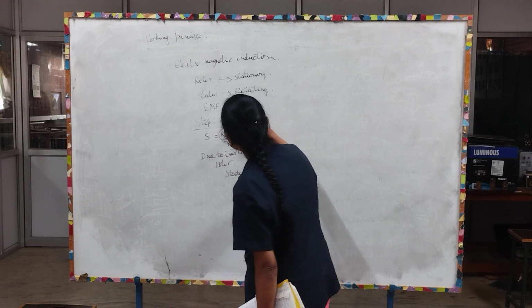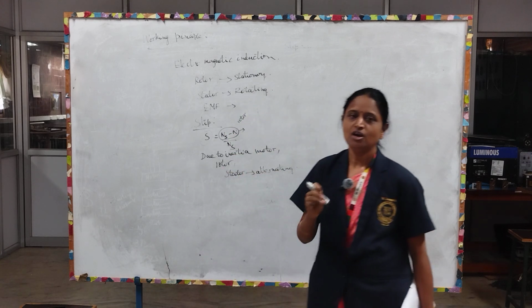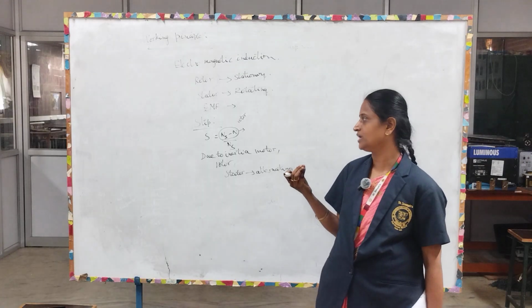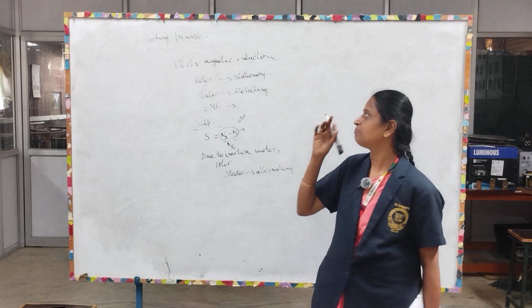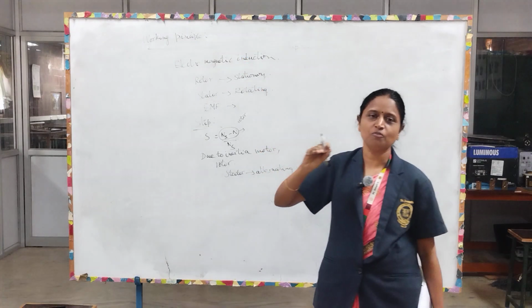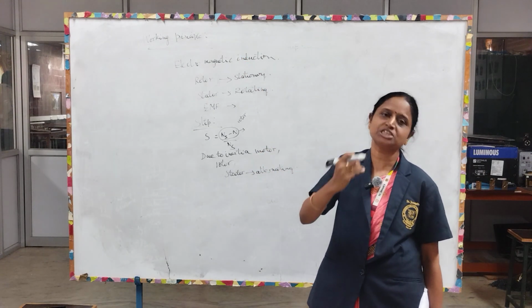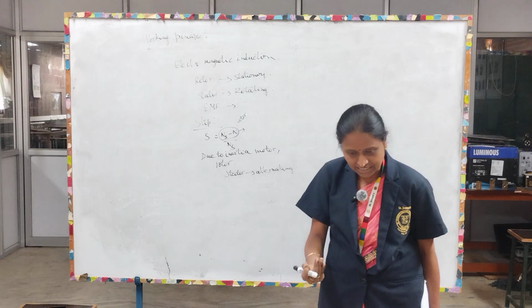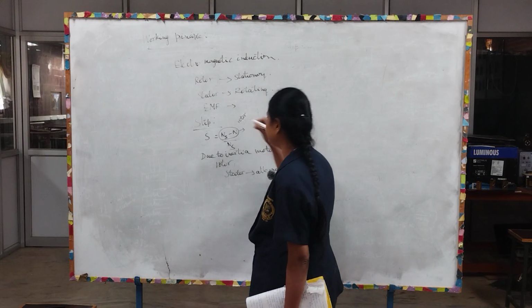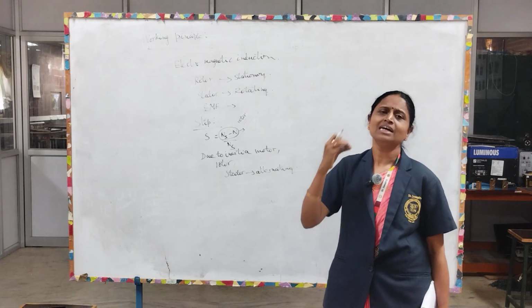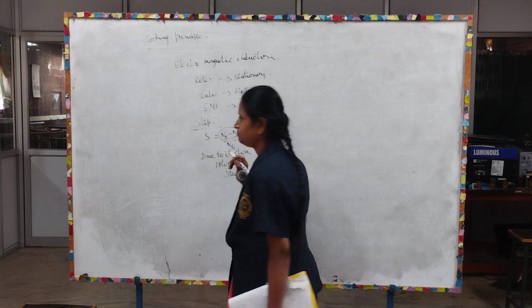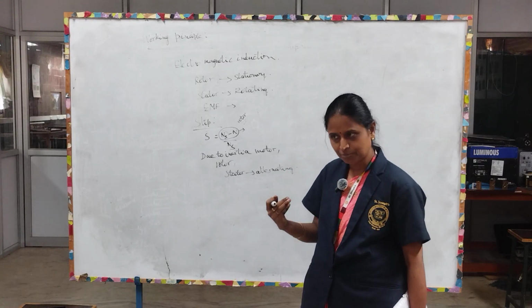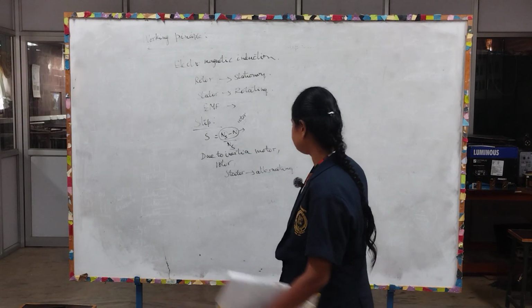N is the rotor speed and ns is the stator speed. Due to the inertia of the rotor, the rotor won't catch up with the synchronous speed. That's why we have slip. This slip concept plays an important role behind the working of an induction motor. That's why we call it an induction motor, because it works on the transformer principle, like electromagnetic induction. The rotor receives electrical power by induction, and the speed of the rotor will be lesser than the speed of the stator. It won't catch up with the stator speed at once, and it takes some time due to its inertia. That is called slip.